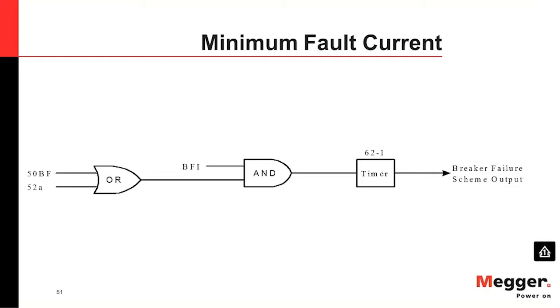Now, testing the breaker failure, we have to do it with our sequencer. Our sequencer will have to create some sequences so that we can test the breaker failure. The pickup of breaker failure is like an overcurrent, but the timers behind it we have to get right, which is the very important thing to finish.